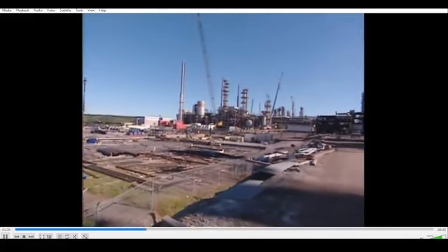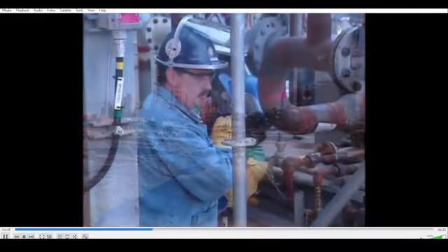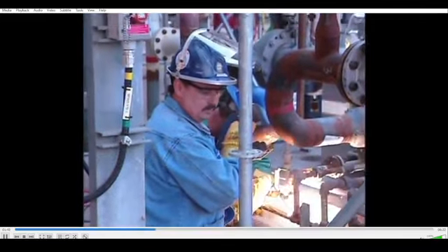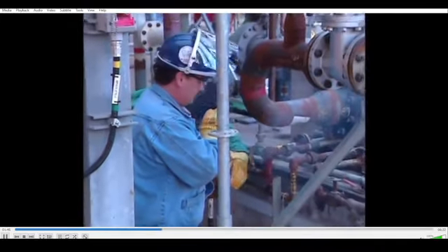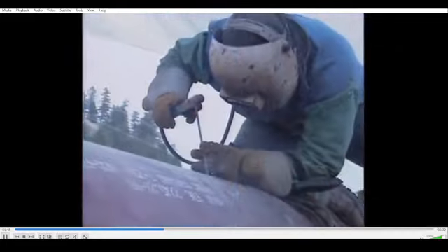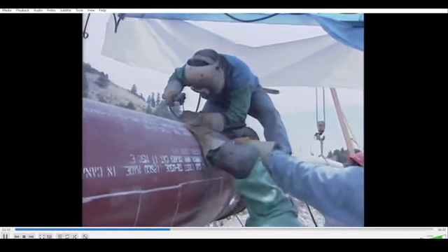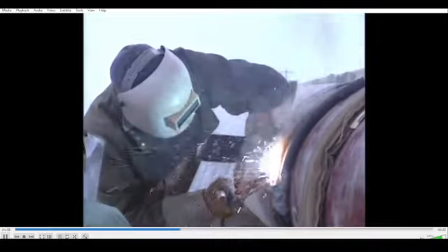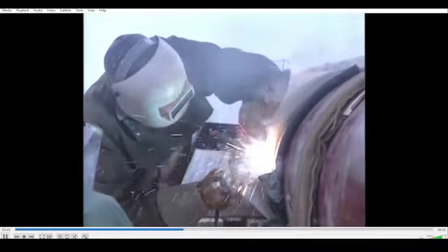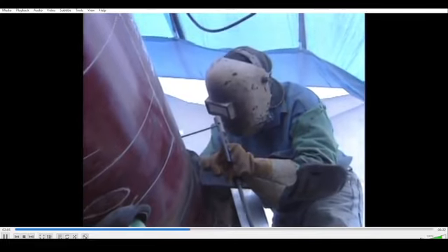Selection is also based largely on the degree of quality required for the weldment. Visual or magnetic particle testing may be all that is needed for verifying weld quality on low-pressure piping. However, radiographic testing would likely be required for critical high-pressure applications. The design, welding, and quality assurance engineers must work together to determine the method of testing and the extent of inspection that meets the requirements of the weldment.